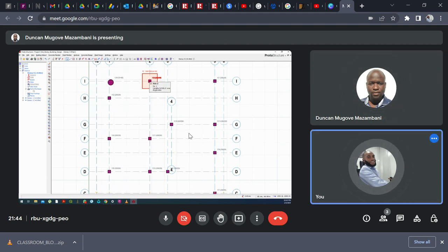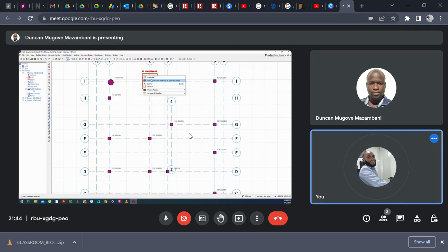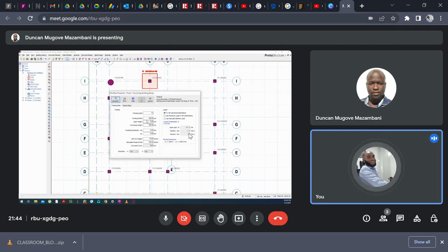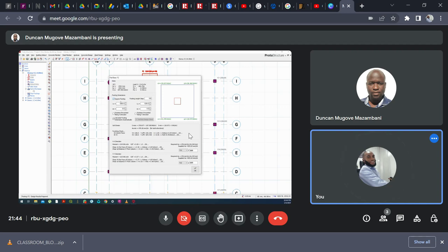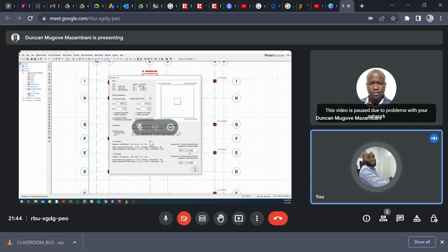So click back on that. No, click back on the right click and say properties. No, click on the footing itself. On the footing itself, okay. Then properties. Then go and change your depth to 300 and then calculate it back. Calculate back. Okay, now on this place, no, hold on, go back there again. Now on this place here, we have done the checking for the punching.